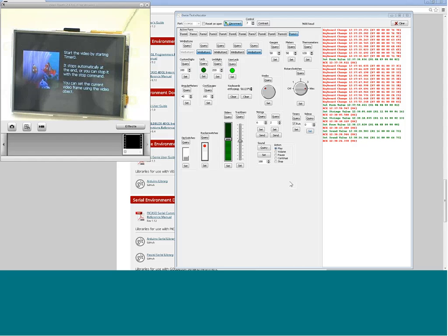But for your applications, for example, you might write something to the SD card. When you're reading, it's okay for the SD card, but maybe the display may crash. So if you restart the program, it really depends on your applications how you handle this. If it's just reading applications from the SD card, I don't see a problem, but the program might crash trying to access the SD card, which just disappeared or got some rubbish in the moment. It tried to read the SD card and you pushed it out.